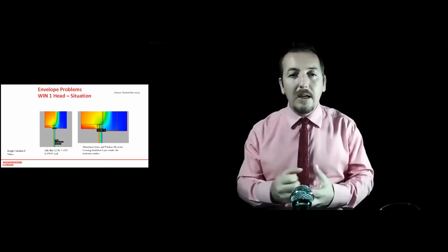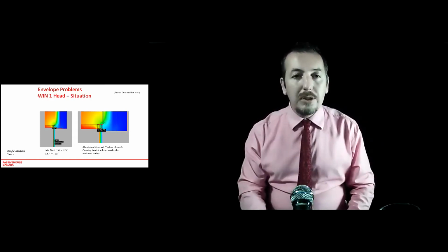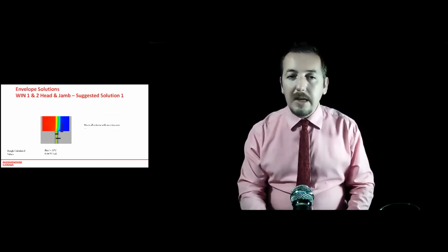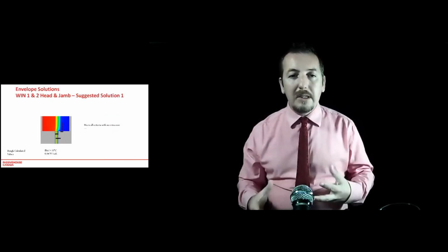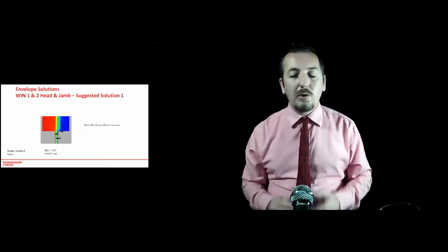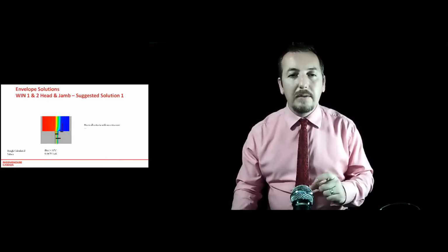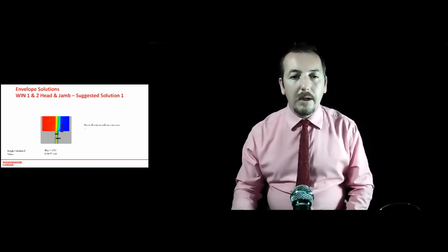It will drag the heat through the aluminium out of the construction. And the solution in this case was to use the same window, the same materials, and just reorganize them in a different way so that the thermal break aligned with the insulation. And that's the crucial element of detailing to passive house, is to align all the thermal breaks, and we actually got 0.04 on this.